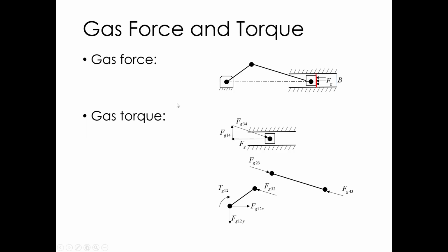All right, so back here, gas torque. This would be the torque about the center line of the crank, the torque from the gas force at the center line of the crank. It's not too bad. So that's going to be the component of the wall force. This force comes from gas, pushes the piston down, and the connecting rod is at some angle. Because it's at an angle, there's got to be a sideways force component if we do a 2-force member approximation of it, which means there's going to be some side loading that results in the wall of the cylinder from this pressure here.